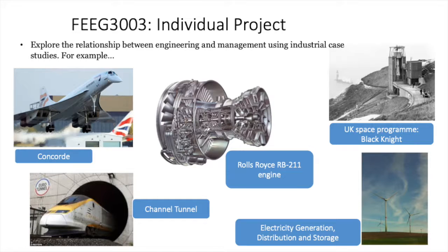With the Rolls-Royce RB211 engine, one of the technical innovations being introduced during its development was the use of a composite material called Hyfil in place of titanium as the structural material for the turbine blades. Whilst this gave a thrust improvement for the engine, it also introduced a failure mechanism because the Hyfil wasn't as stable or strong at high RPMs as the traditional titanium.